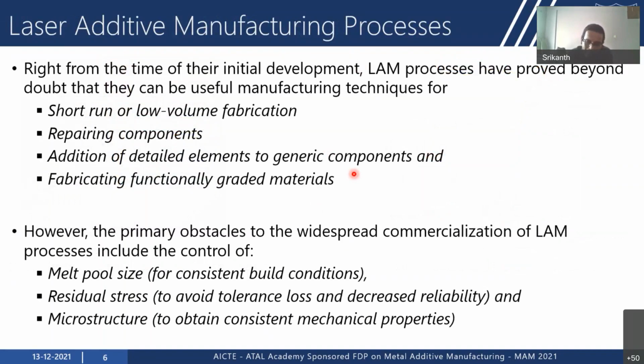Both the technologies, right from the time of initial development, have proved beyond doubt that they can be very useful manufacturing techniques for low volume production. LDED is very much suited for repairing components because you can deposit material on any 3D surface, or you can add material to existing components, and you can also fabricate functionally graded structures. So LDED is most widely used for repairing components, adding material to existing components, and fabricating functionally graded structures, whereas the laser powder bed fusion process is used for direct manufacturing of components because you have better resolution and better surface finish with the LPBF process compared to the LDED process.